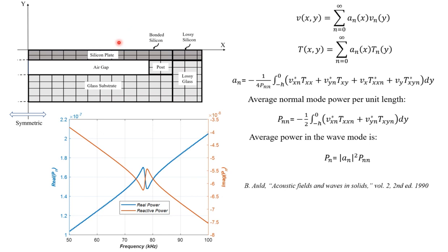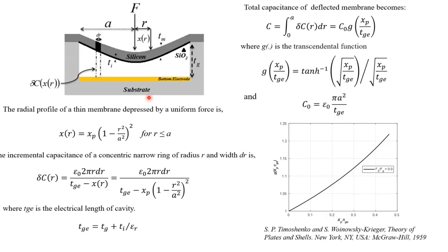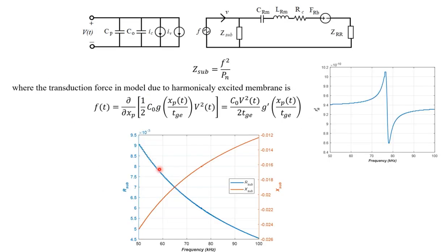So it is radiating into two acoustic mediums, very different mediums, because the materials are different. One is the fluid, having Poisson ratio close to 0.5, just like soft polymers, RTV rubbers, and the other is the glass, having Poisson ratio 0.2. So the radiation resistance is like this for the glass medium, which is very thin.